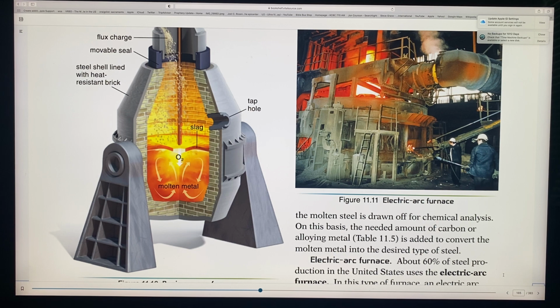And in the midst of oxygen processing, the basic oxygen process is refining this pig iron to steel. And they put this in the chamber, as you see there, with these magnesium and calcium oxide bricks outside. And it can hold over 300 or more tons.